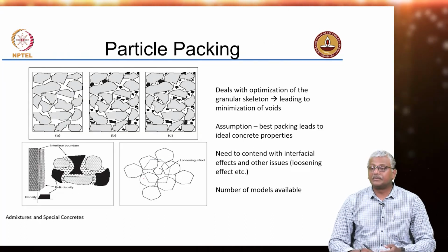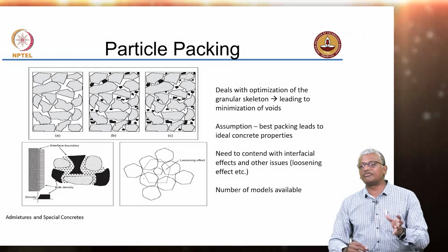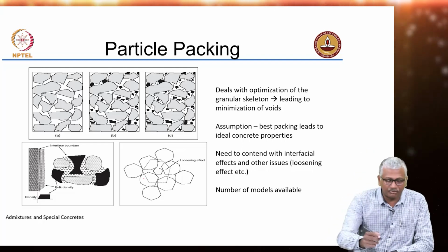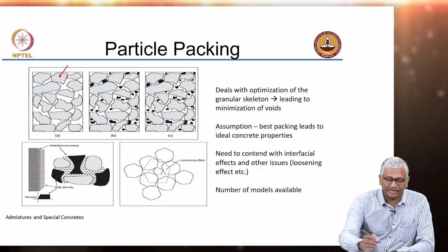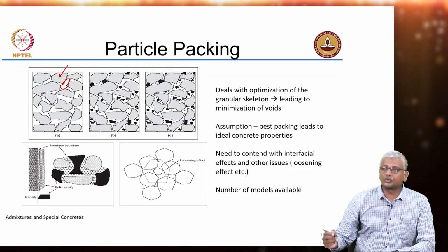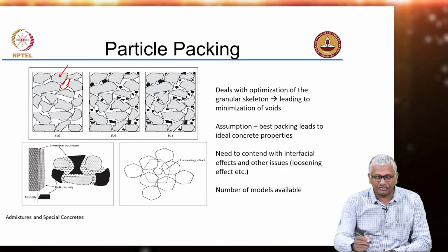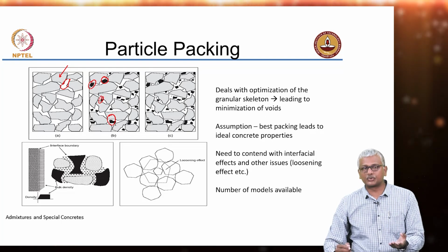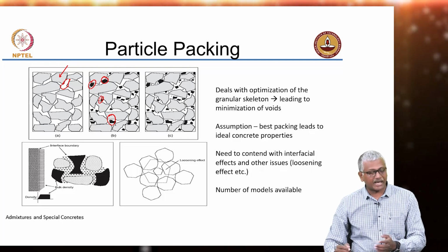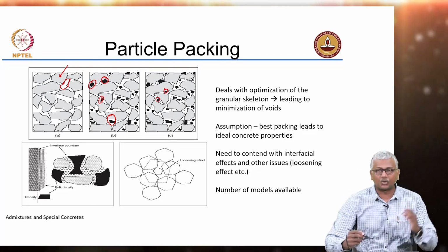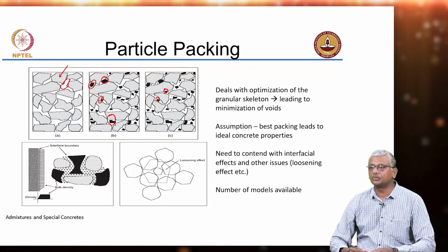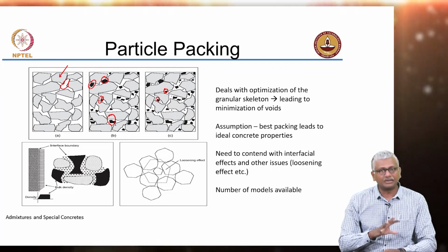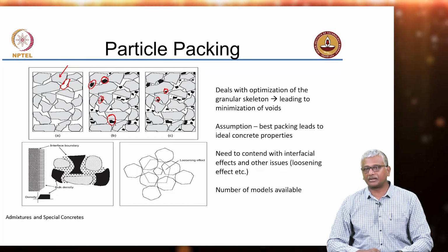And for this, people have looked at various ways in which you can start filling up a volumetric container with sizes of materials that are progressively reducing. Let's say you fill up with coarse aggregates first, you have gaps between these coarse aggregates, you choose your next particle size in such a way that it can start filling up these gaps, right? And then you still have gaps after you choose that material. You fill up those gaps with even smaller particle sizes, and so on and so forth ad infinitum. So the idea is that you progressively keep on filling up your volume with smaller and smaller particles so that you get a maximal filling up of the particle space.